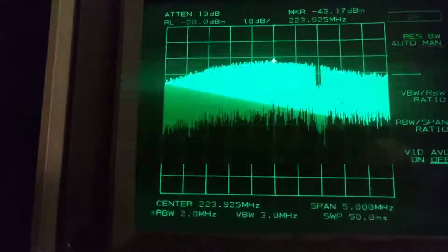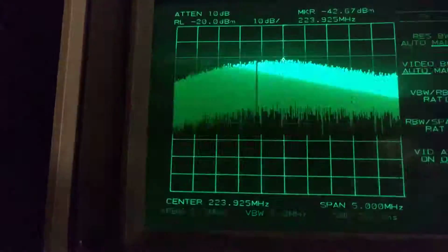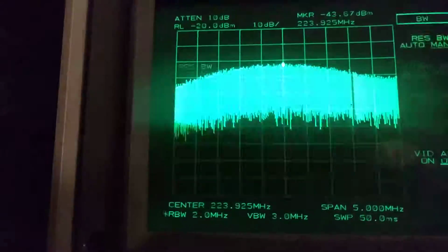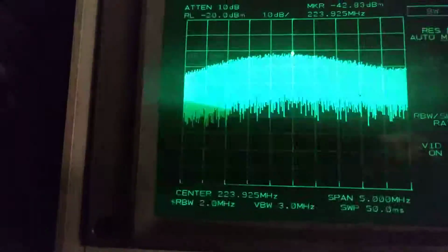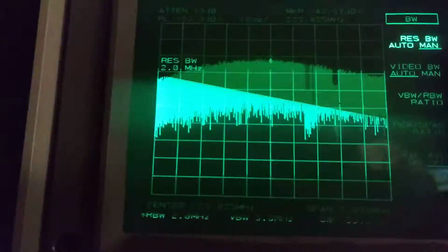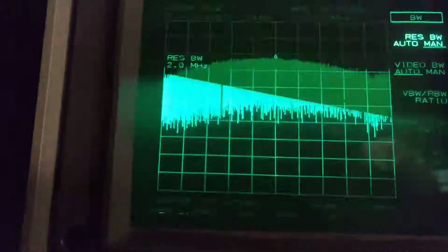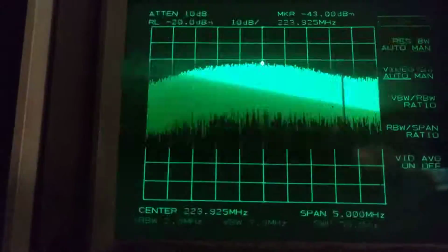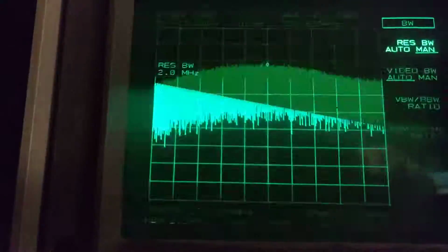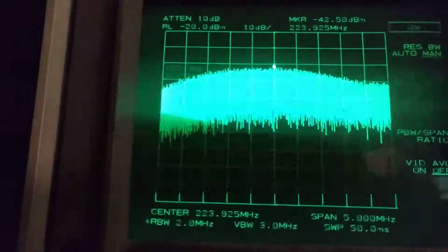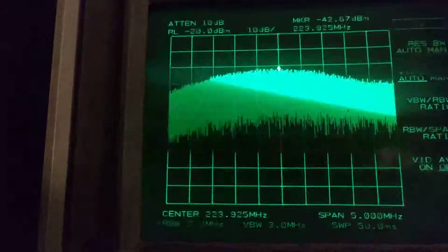Of course, being an OFDM, that is a mix of modulation, you also see sometimes a blank coming in, where it is possible for other transmitters to broadcast on the same frequency, SFN, single frequency network. Okay, but this is out of the scope. The scope is to demonstrate that for measuring the power of one signal, it depends on what signal it is.